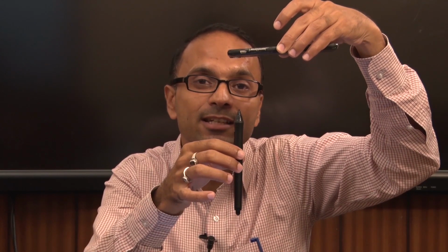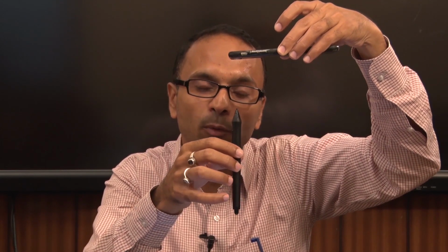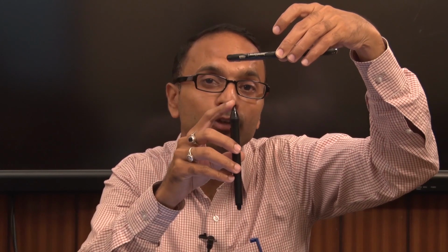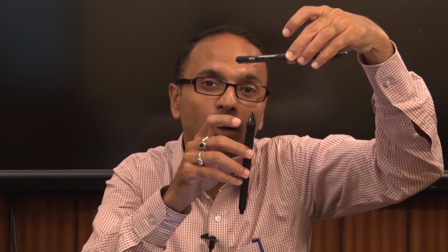If you take the radial distance from the center to the image of the bottom point and the image of the top point on the photograph, you will find they are lying approximately on one line, assuming that there are no distortions in the optical axis. So, radially they are outward.